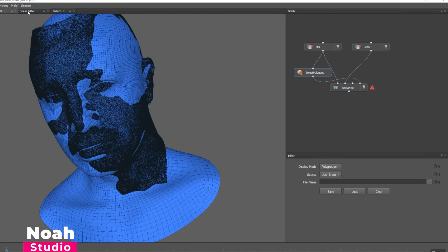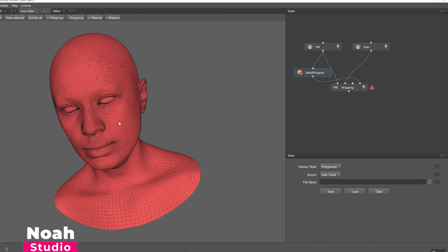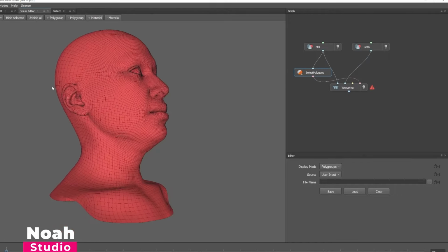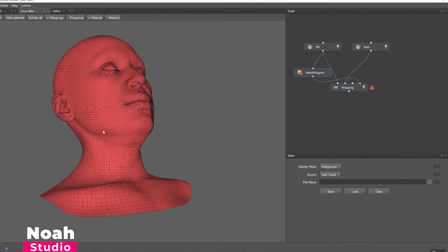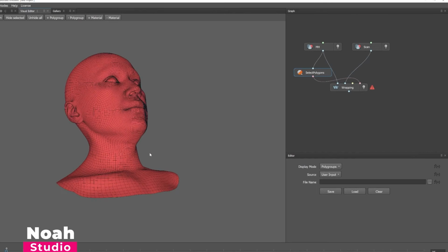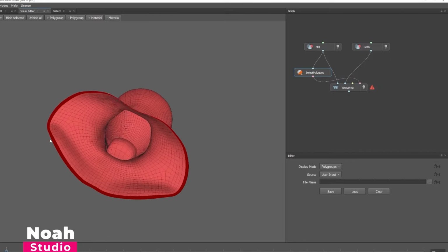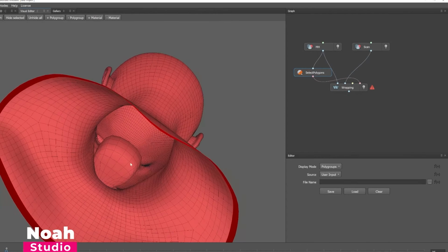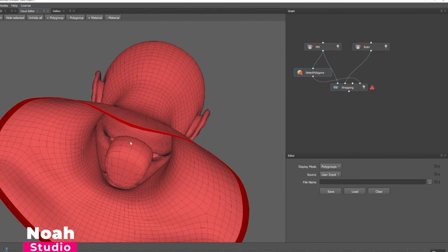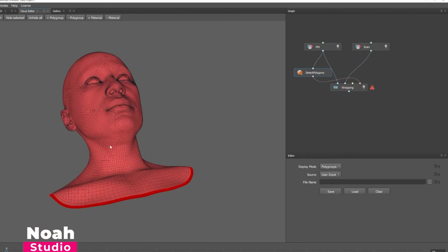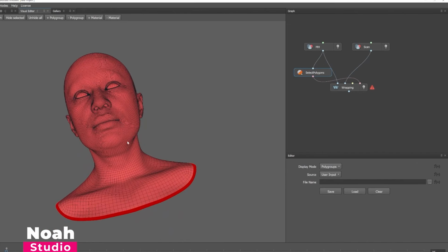Then let's go to the editor. This is the Metahuman, and let's select the polygons to exclude. Let's select, double click. Just select a couple of polygons, and then grow the selection. Let's select this inside. When we grow, we'll bring it up to here.